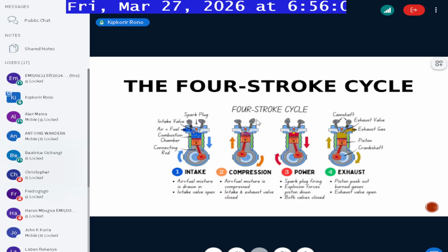So the work of the carburetor or any fuel injection system, like an electronic fuel injection system, is to atomize. The next thing is that it also premixes air and fuel in a definite ratio. That ratio, we call the air-fuel ratio, so you need to remember the term. The air-fuel ratio is a specific ratio in which air and fuel have to be mixed.